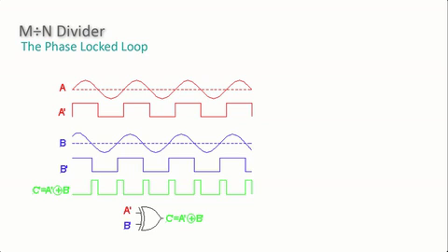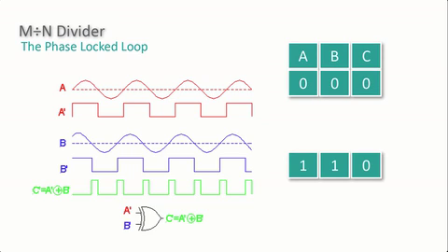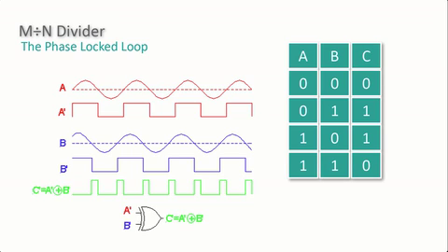Now here's an example of a really simple phase detector, an exclusive OR gate. Now, exclusive OR is one of the fundamental logic operations. When both inputs are 0, or when both inputs are 1, the output of the gate is 0. But when the inputs are different, the output of the gate is 1. In this example, we assume that the XOR gate has inputs that sense and switch to 0 when the input signal goes below ground, and switch to 1 when the signal goes above ground. And that means that the gate sees the input sine wave as though it's a square wave with transition points where the sine wave crosses ground.